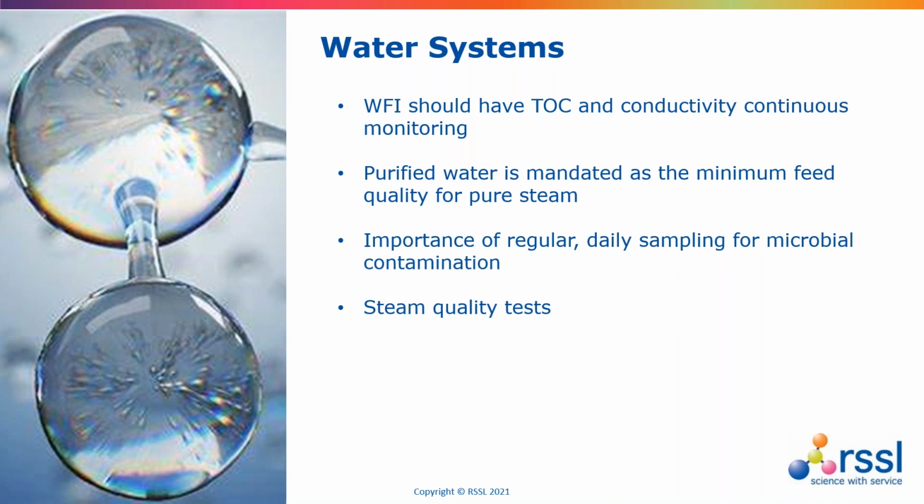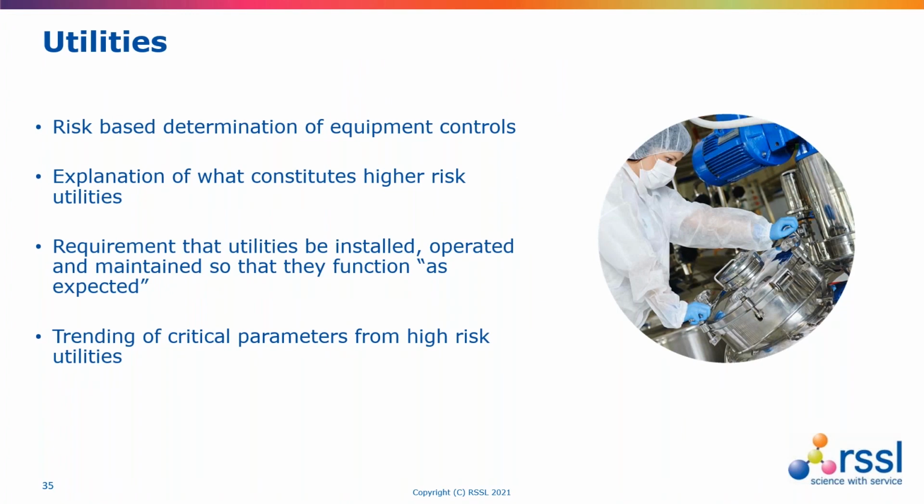And that not only includes microbiological testing, but needs to extend to total organic carbon and conductivity testing as well, and also controls around clean steam and steam quality. And that extends quality risk management to water systems and to all utilities in total, and that also includes reference to ensuring that there are suitable diagrams and knowledge about the system, and that any changes or add-ons are fed back to the original design concept.